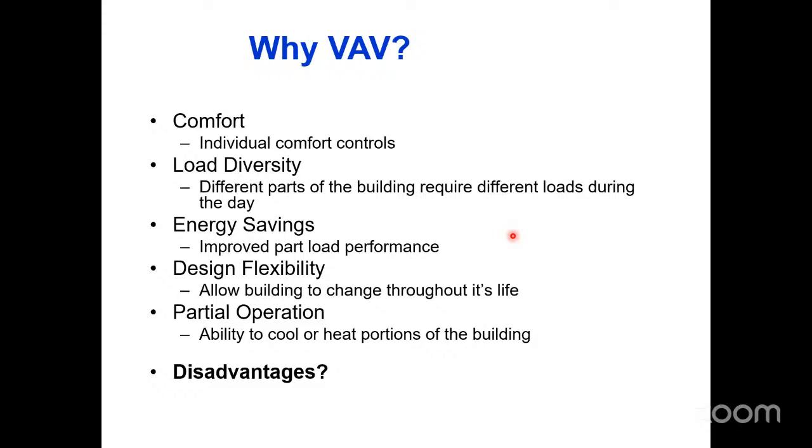And you have the ability to stage things down. Like if some of the people in the office leave at 4 o'clock, you can put their thermostats in setback, but other people are there till 6:30 p.m. Those stats can continue to be in occupied mode, and you can take advantage of not fully heating and fully cooling every area at the same time.